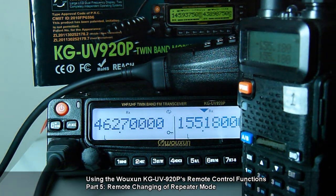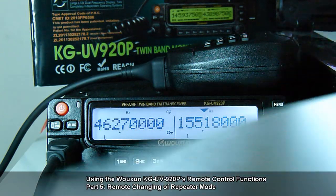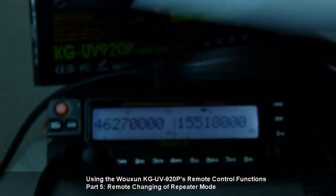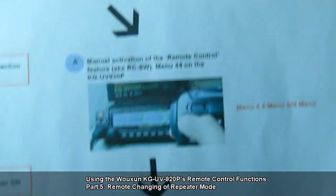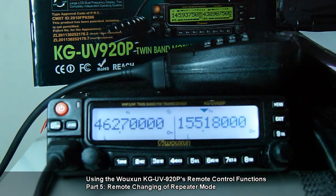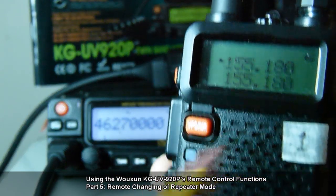Now, we are now in two-way crossband repeater mode. What if we would like to go back to normal communication mode? So what we do again is use the matching mode code of 1031 after doing procedure B and 3C. So let's try it again. Our master frequency, our controller.